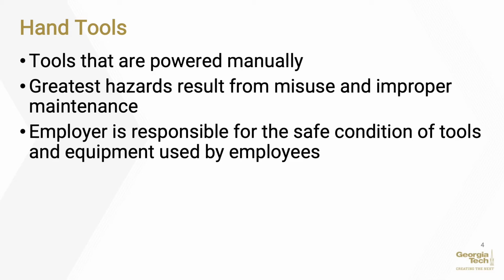Impact tools such as drift pins, wedges, and chisels must be kept free of mushroomed heads, and the wooden handles of tools must not be splintered.